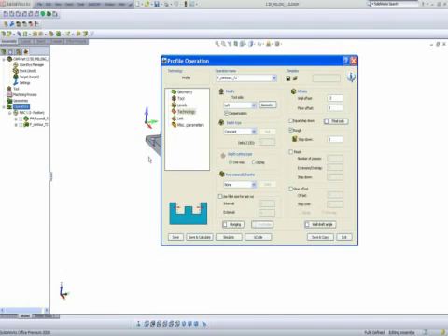Since I'm going down all the way on the outside, I do not need a floor offset. And my finish, I'll also be going down in one step. Now my step down in my rough, I can have at 3mm. And my finish, I'll leave at 0 since I'm going down all the way to the very bottom.